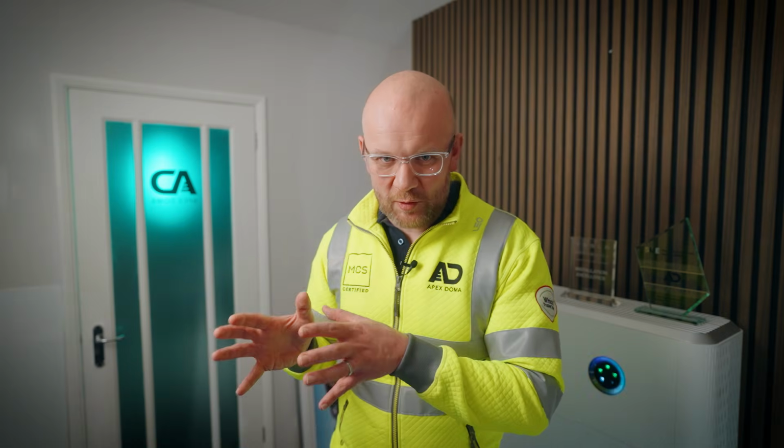You can also install inverters and battery storage for people who can't have solar panels, or maybe you're having an extension on your house and you're not quite ready for them. You can install battery storage by itself. So you don't always need solar panels to wire into an inverter. With a battery-only system, you still need an inverter. You still need the engine. Think of the battery as a little bit like the fuel tank.